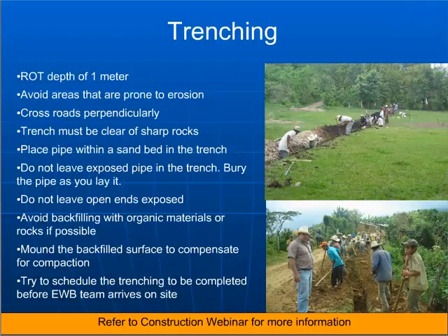Another consideration as far as trenching goes has to do with rainy season versus dry season. In certain climates, if it's a clay soil during the dry season, the ground may be so hard that it can hardly be broken with a pickaxe. But then if you come back 2 or 3 months later during the rainy season, it's nice and soft, and everything can get done very easily.